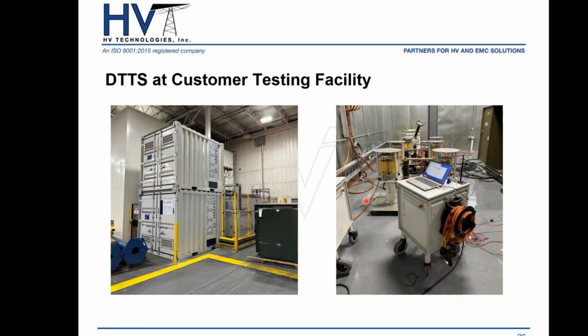Again, the frequency converter has the highest accuracy, and it's completely calibrated and certified from the factory. We have very low system noise as far as partial discharge, so partial discharge measurements are highly sensitive.